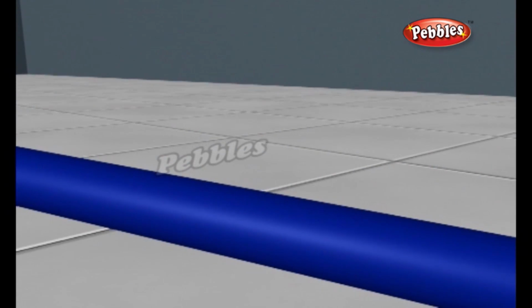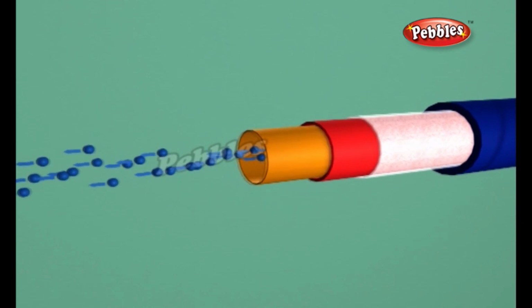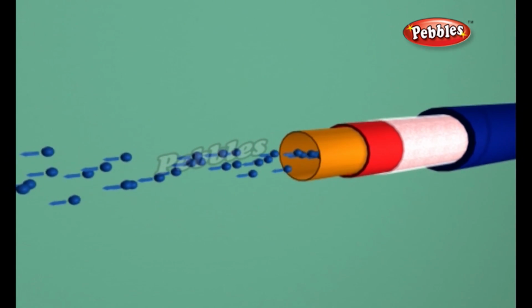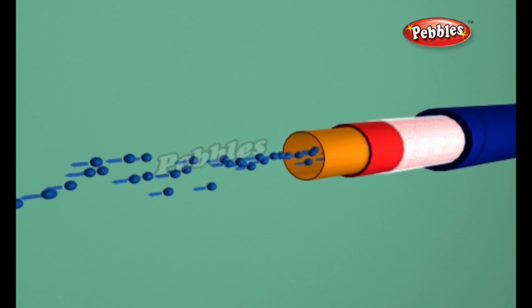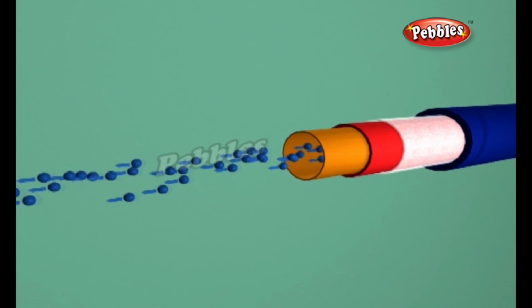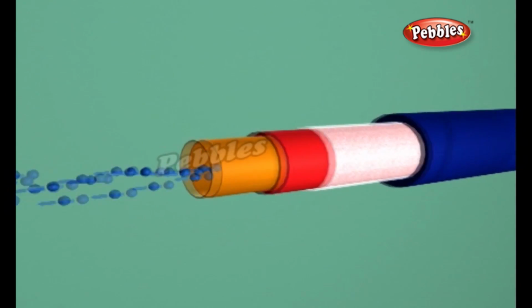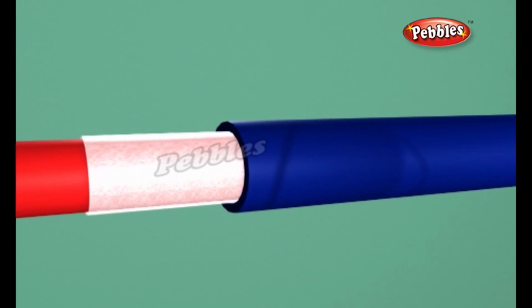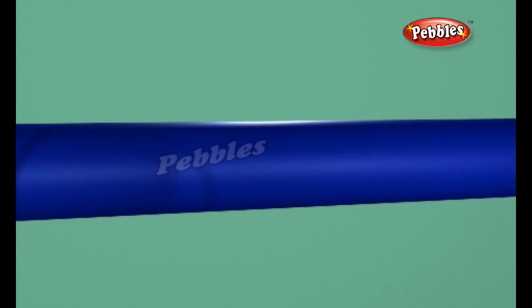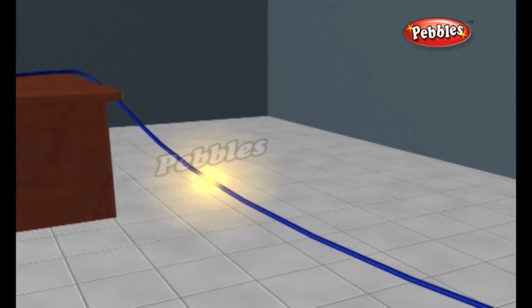Optical fibers carry light signals down them in modes. A mode is the path that a light beam follows down the fiber. One mode is simply to go straight down the middle of the fiber. Another is to bounce down the fiber at a shallow angle. Other modes involve bouncing down the fiber at other angles more or less steep. Optical fibers are widely used in fiber optic communications, which permits transmission over longer distances and at higher bandwidths than other forms of communications.